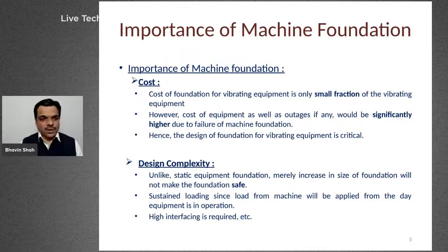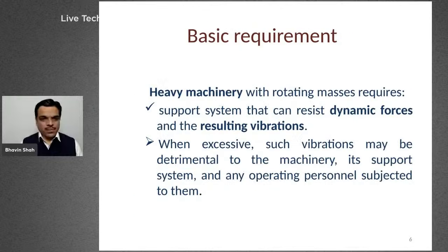So what is the basic requirement? Somebody mentioned this point: what is the basic requirement whenever we are designing the machine foundation? For heavy machinery foundations with rotating masses, whatever support system we provide must resist the dynamic forces generated from the machine, which ultimately result in vibrations. Whenever this vibration exceeds the permissible limits, it could be detrimental to the machinery itself.